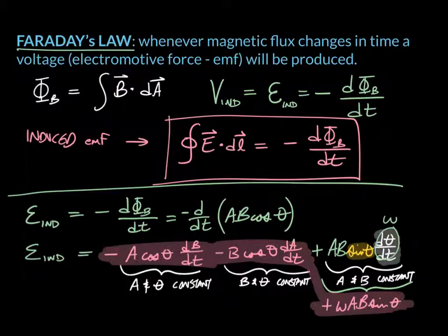And so from a standpoint of, if you were accounting for this in some control system, as long as you have your magnetic field strength inputs, what would you need in the code? You would need to know the area, you would need to know the magnetic field strength, you would need the angle of inclination, and you need every one of those coordinated in time. You need 4 pieces of information going into the computation in your control system. It's easy math, and sensors will tell us all this, and if the area is fixed and the angle is fixed, then you just put the number in place. All right?